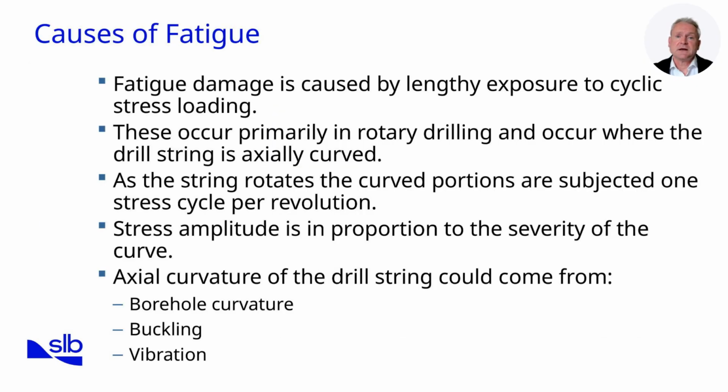Fatigue in drill strings occurs when steel is subjected to repeated cycles of stress that eventually weaken the material. Unlike a single overload event, fatigue is a silent process that develops over time, often without obvious warning until failure occurs. In rotary drilling, the primary source of cyclic stress is curvature in the wellbore. As the drill string rotates, any curved section is repeatedly bent, creating alternating tensile and compressive forces with every revolution.